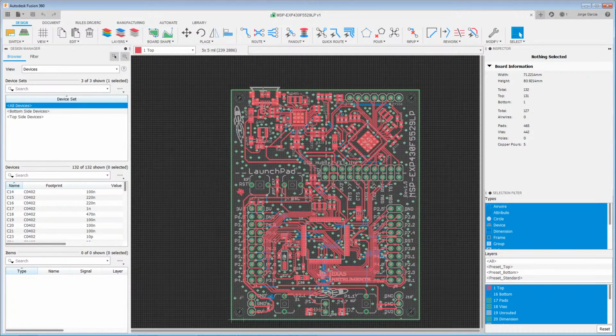So the goal of this webinar is going to be very, very tightly focused. The idea is that we're going to go over manual routing. Now, one may think that it's a very simple concept, and it is. It's just taking copper from one connecting point to another. But this engine on its own, we can spend several hours talking about. So I'm really just going to focus on the first mode, which is route manual. If you can understand route manual fully and what it's capable of, then the other tools that build on it are easier to understand, because the same shortcuts and workflows apply.